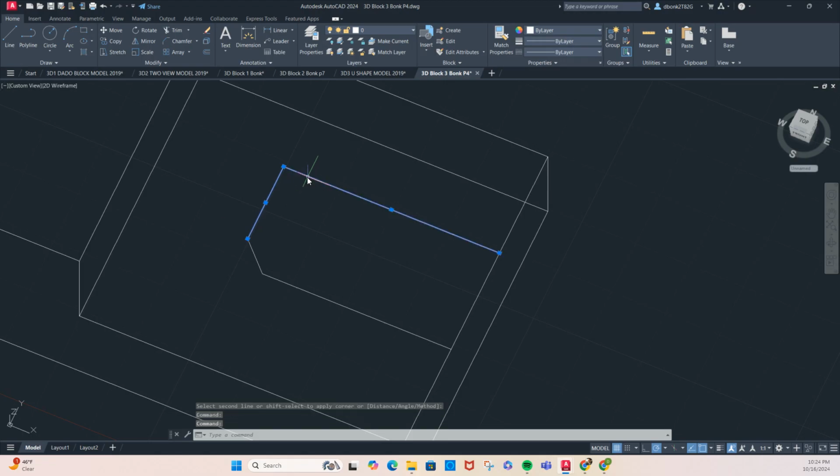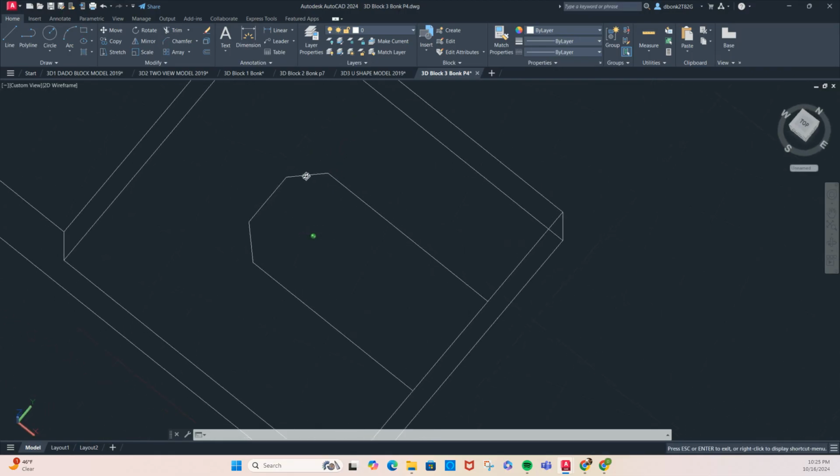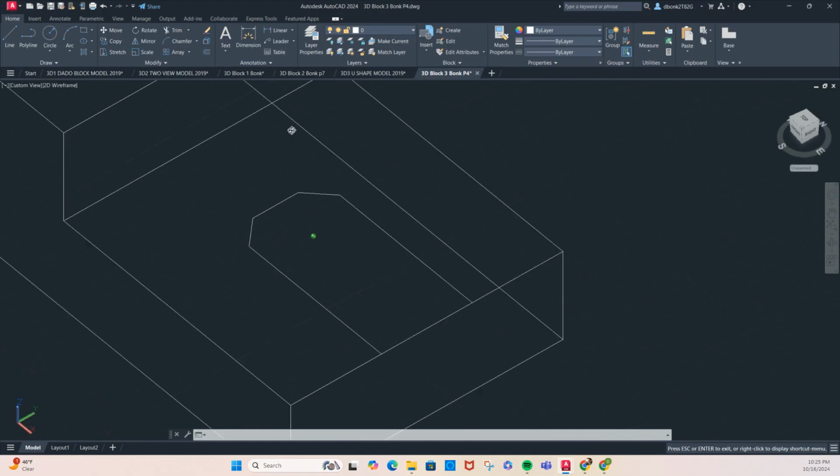If you just try and do this again, it won't work. But it will hold on to the measurements that you just put in there, and you should be able to just click these two things again. It's always going to remember your previous distances that you entered. So if you do a distance setup with a chamfer, like we did here, you click the chamfer tool again, and the next time you click two lines, it's going to chamfer it the same way it did the last time. If you're changing it somehow, you have to change that.